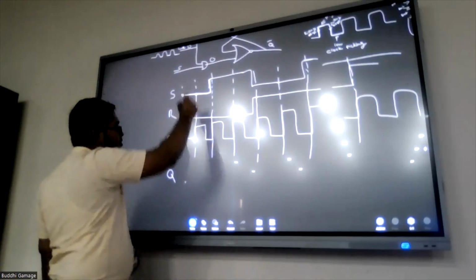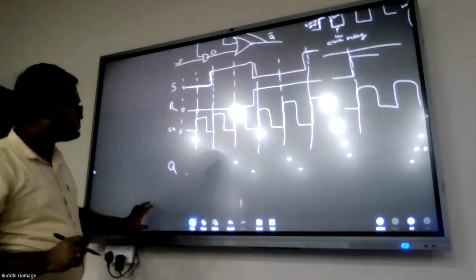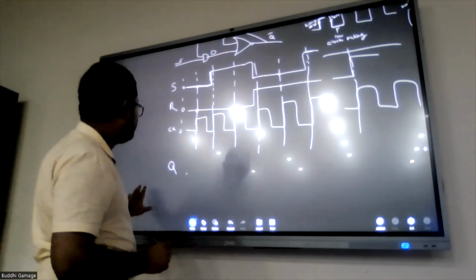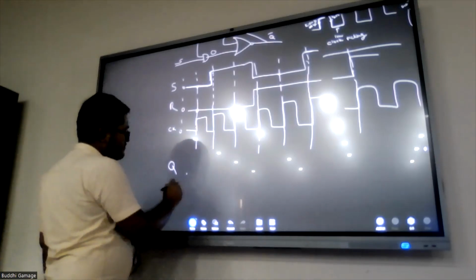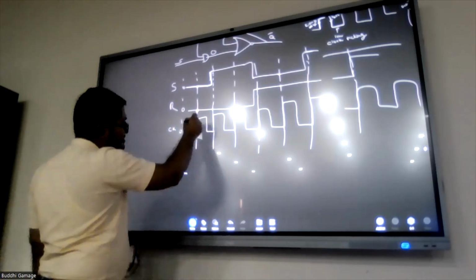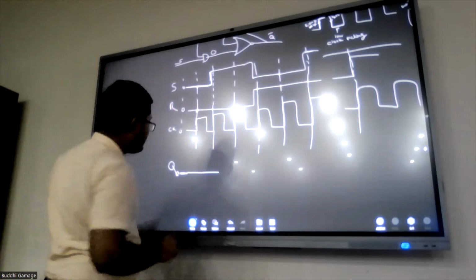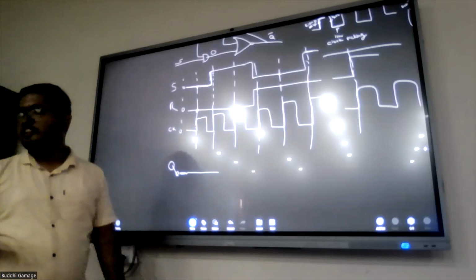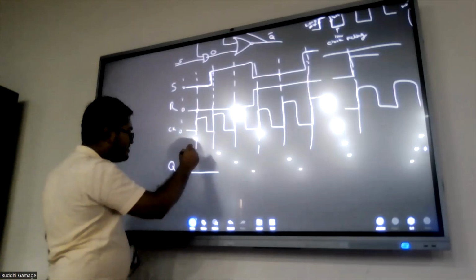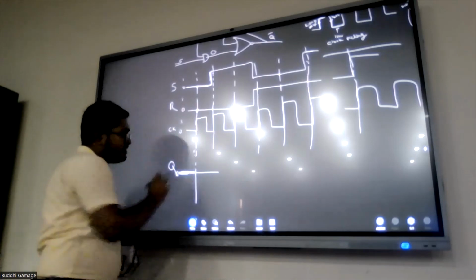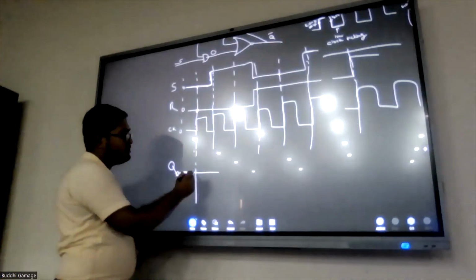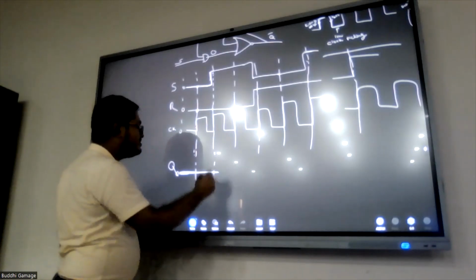So in this particular case, both are 0, right? So since this is also starting from 0, in this case it will also continue, right? Because it gets the previous state, right? In this particular scenario where this tick happened, our previous Q is 0, right? This is the previous Q. So since it is 0, the next Q will also be 0 up to this tick.